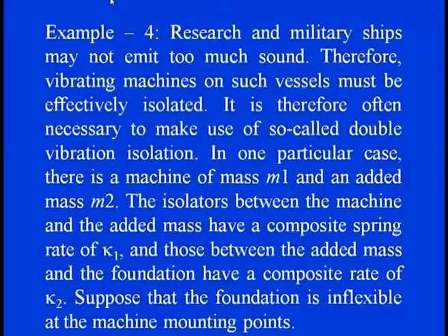these exciting frequencies. In the next model, now we can say that we have a military ship which is moving at a certain speed, and the vibration machines of such vessels must be isolated. And for that, you see here, we need to take a necessary action. We can say some kind of double isolation, or even in the railway feature also, we know that when the excitations are so high and we just want to comfort the situation inside the cabin, there are double isolations.